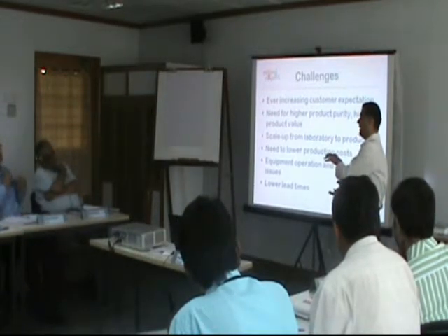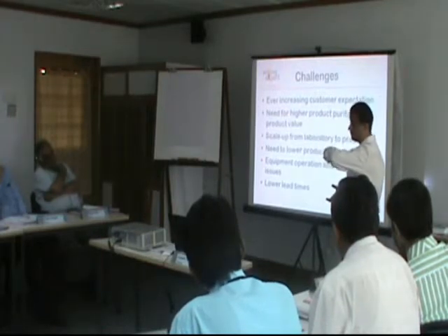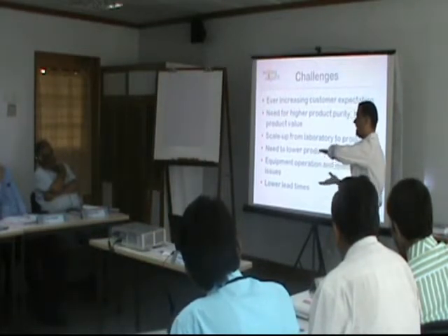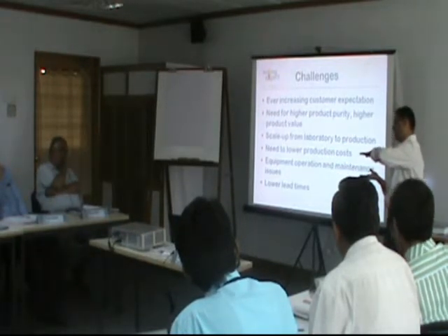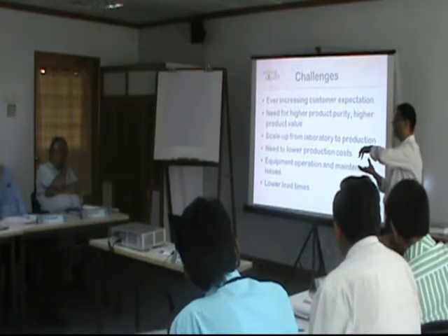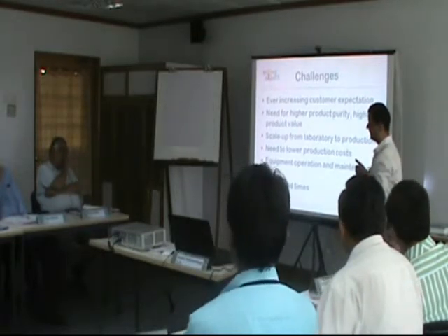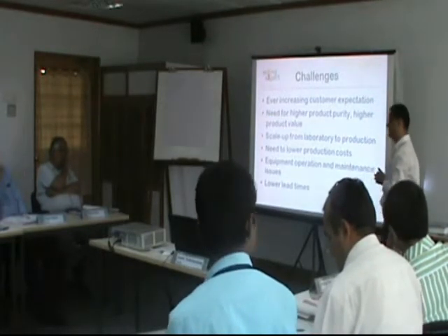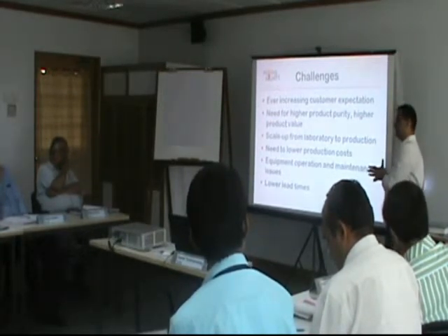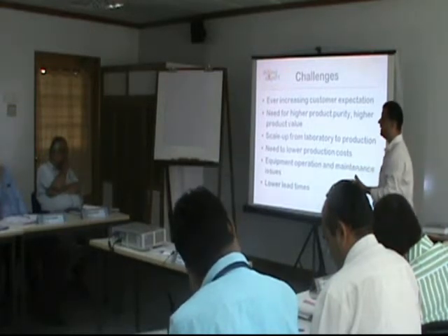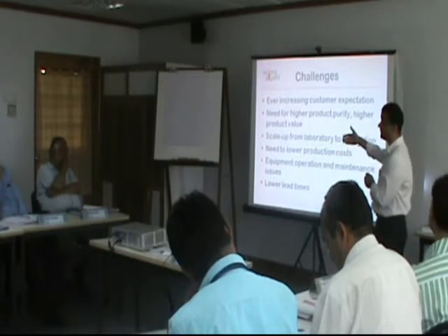Finally, when the material is packaged, the process of final packaging and the process of mixing are to be brought as close as possible. It is only in that way that you can prevent segregation. Once your material is mixed, as you did mention, you can add certain agents to affect the material characteristics, to affect the phase in which the material is. As you said, you would need a binder, something which holds these materials, otherwise they would separate. So it all depends on the process and the formulation.